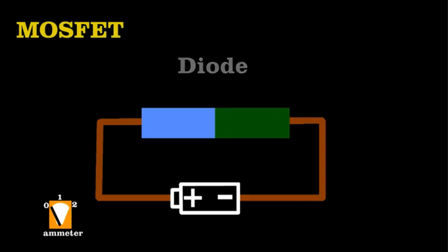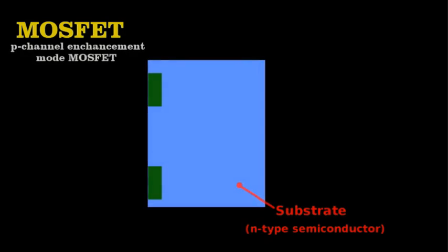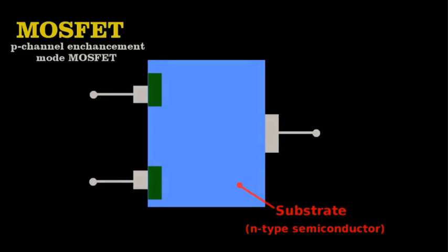Now, to build a MOSFET, we take 2 such diodes and put them together so that each is reversed. Now, this seems useless because no current will ever flow through such an arrangement. But engineers embed this diode sandwich into the same type of semiconductor as the diode ends that touch. Then they place metal contacts at the ends of the diodes and on the block of semiconducting material.